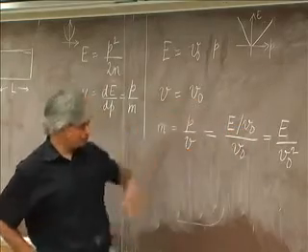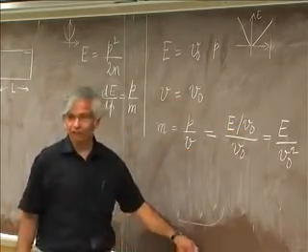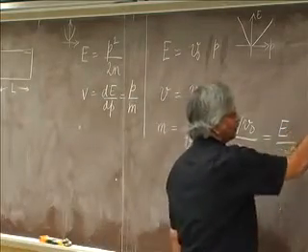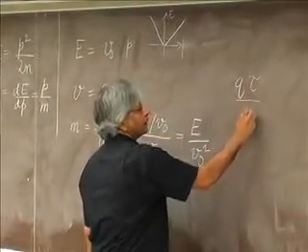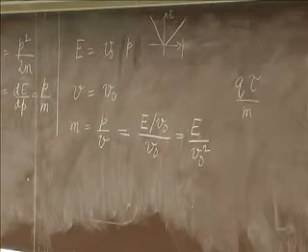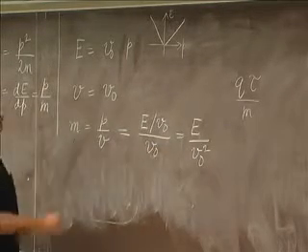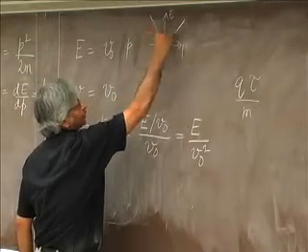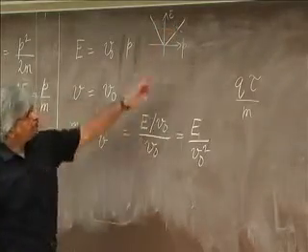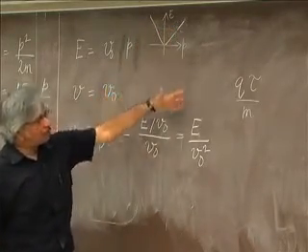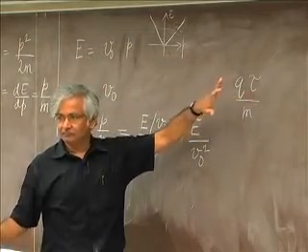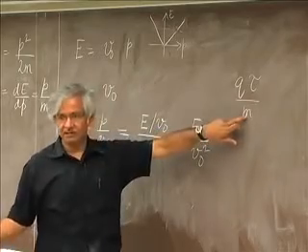So the point is, as the energy increases, the mass increases proportional to the energy, essentially. So if you are trying to use a formula like, let's say you're talking of mobility. Mobility, you usually think of it as q tau over m. And as electrons have higher energy, let's say because you increase the carrier density, the Fermi energy is going up, and so the average energy of the electrons is higher. And usually as you go up, if the mobility goes down, you say that maybe the scattering time, the mean free time, is going down, but not really. It could be just because the mass is going up.